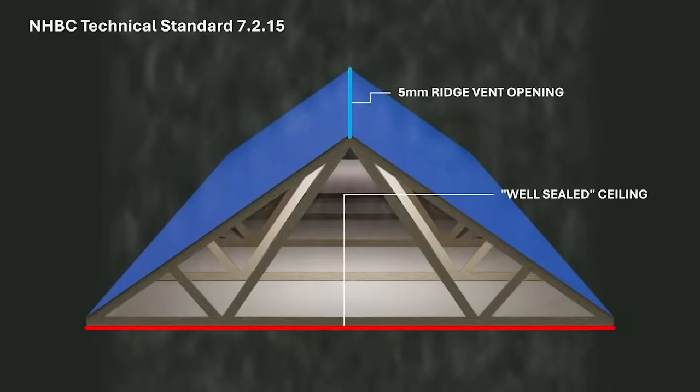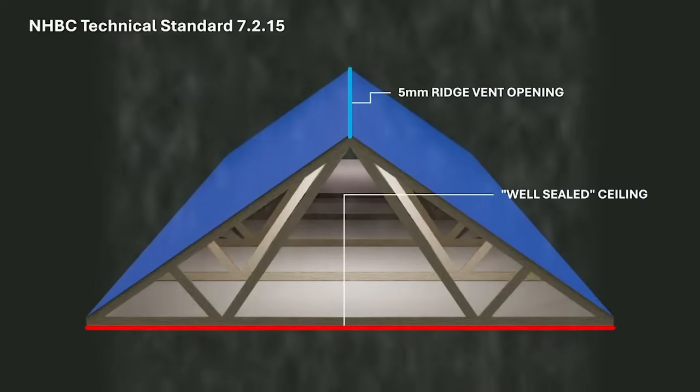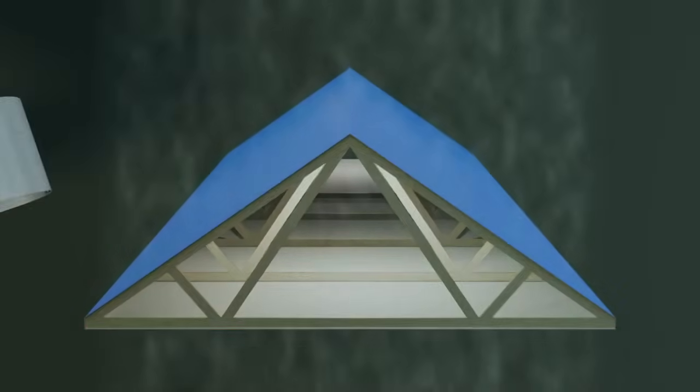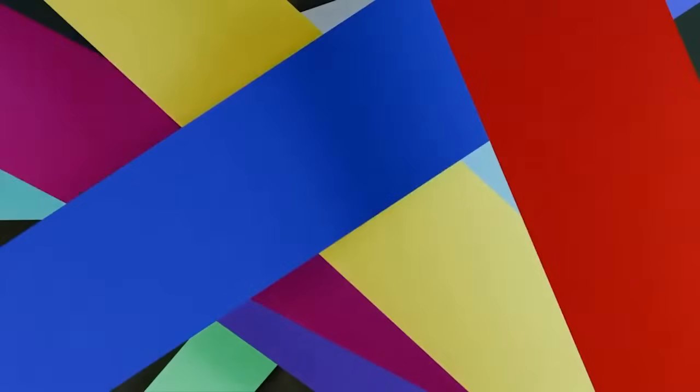It's not clear, however, how effective this type of ventilation is, given no airflow into the loft is possible through the well-sealed ceiling assembly or the airtight underlay. It's also important to bear in mind that whilst it might seem like all LR underlays are interchangeable, this is often not the case, and the third-party certification for each membrane can include some important differences. A good example of this is when we consider the air permeability of membranes. While specific guidance regarding air permeability was included in the initial drafts of the 2020 BS 5250, it was latterly removed, leaving these important additional considerations to be dealt with via third-party certification only.